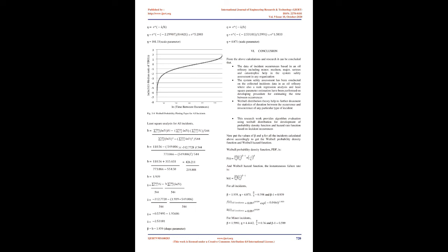The Weibull distribution is frequently used in reliability work to fit failure data because it is flexible enough to handle decreasing, constant and increasing failure rates. Probability is represented by the area under the curve of the density function, which is calculated by an integral, and thus the median of a continuous distribution is the point on the real number line where exactly half of the area lies to the left. The mode of a continuous probability distribution is the point at which the probability density function attains its maximum value. See Weibull distribution.